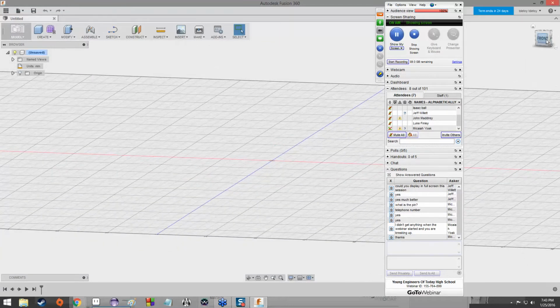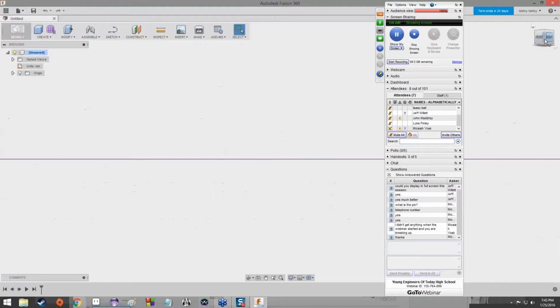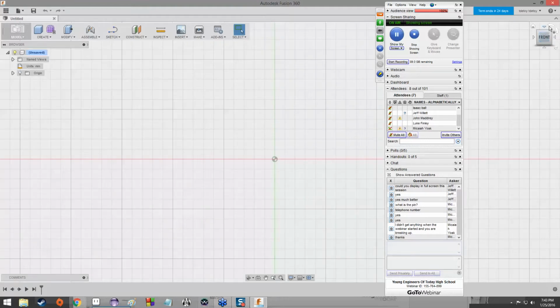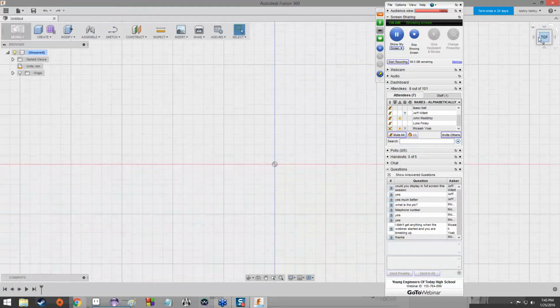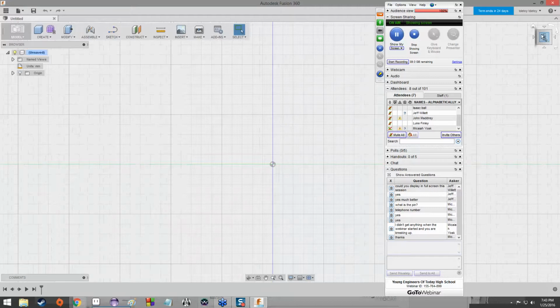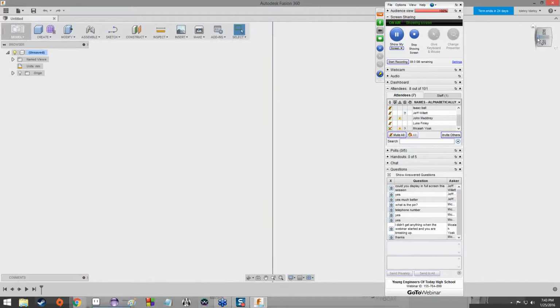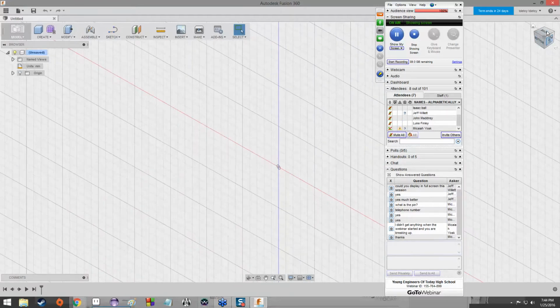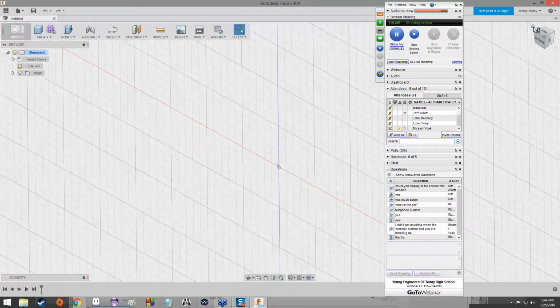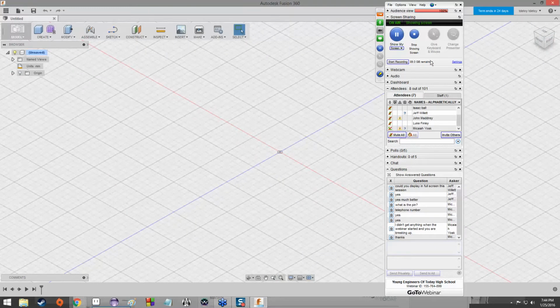Now, there's another way to do this. You'll notice that if I mouse over any of these parts of the cube, it will highlight it. So we can actually just click on one of those and bring it directly to that point. We can go down the left, and then to the left edge, left back edge, and then the corner between the left back and bottom. And then we can click on the home in order to bring us back to the original rotation, all that kind of stuff. So that's, again, very useful for navigating around your 3D model.